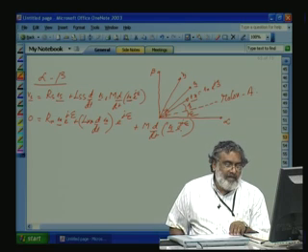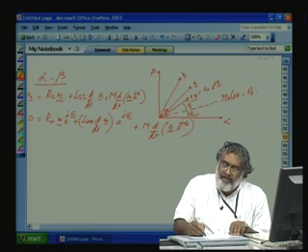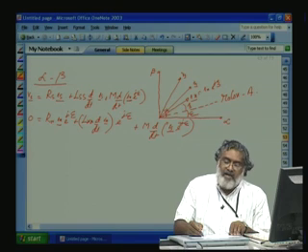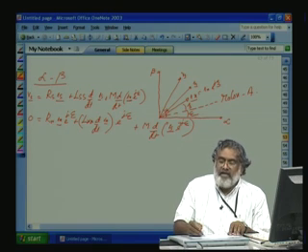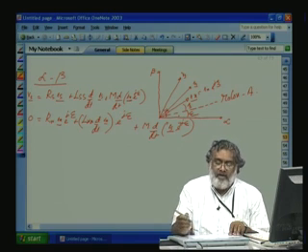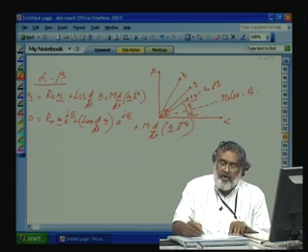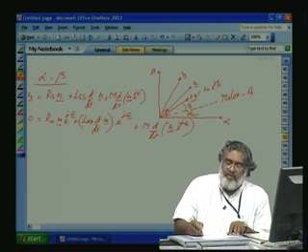This is the stator current. This stator space vector Is, defined with respect to the stator, is multiplied by e raised to minus j epsilon as it has gone to the rotor axis. So you get the component of the stator current which is contributing to the induced voltage in the rotor, multiplied by m into d by dt.